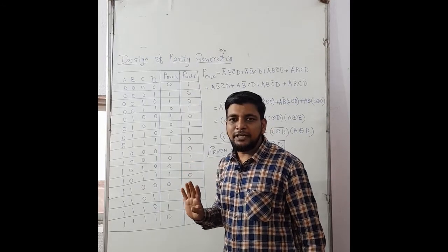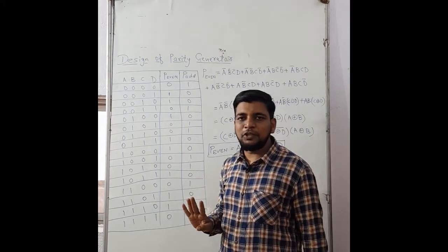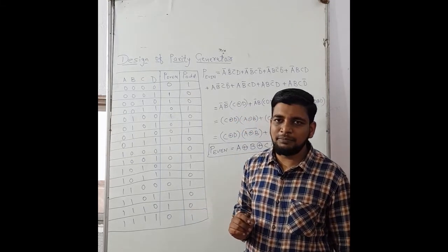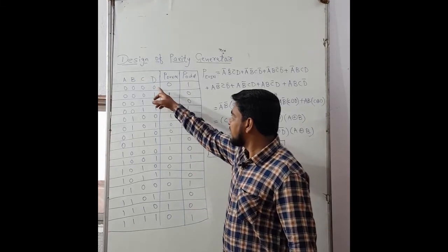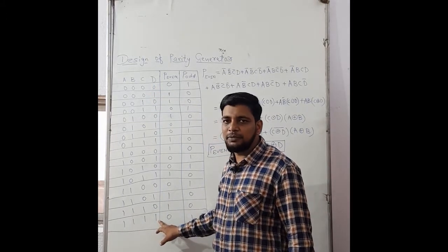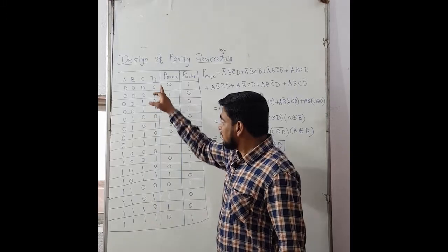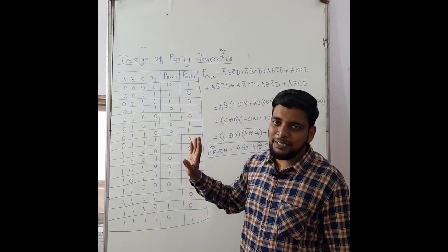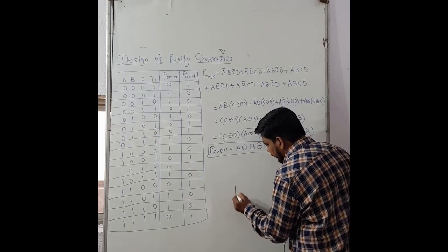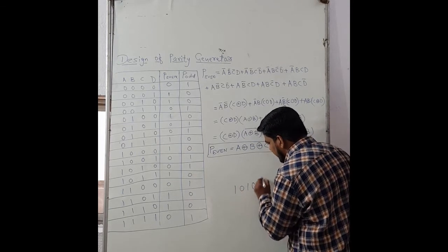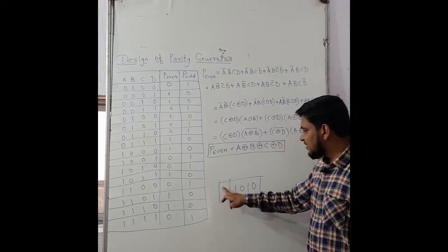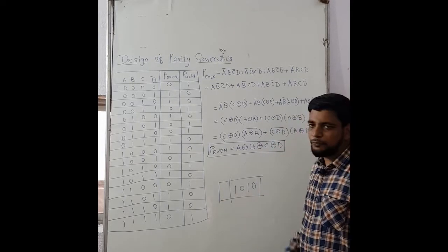When the information is 4 bits, the possible combinations are 2 raised to 4, that is 16 combinations, starting from 0, 0, 0, 0 and ending with 1, 1, 1, 1. As we have already discussed about the parity methods, we add one extra bit to the information, and this extra bit depends on the number of ones in the input information.